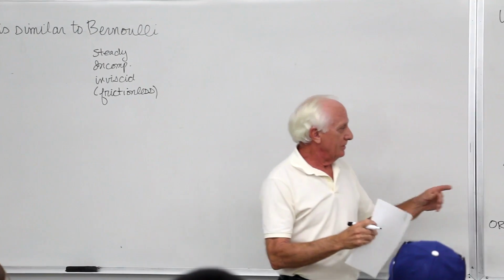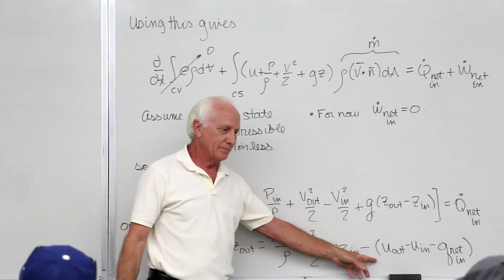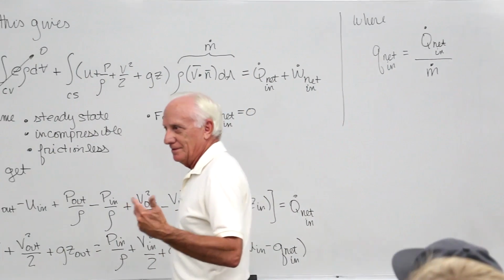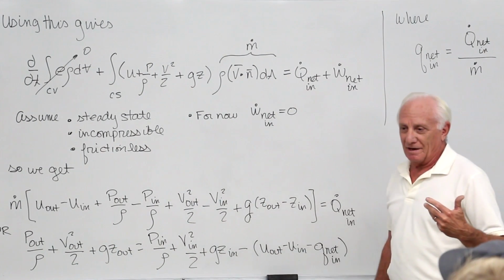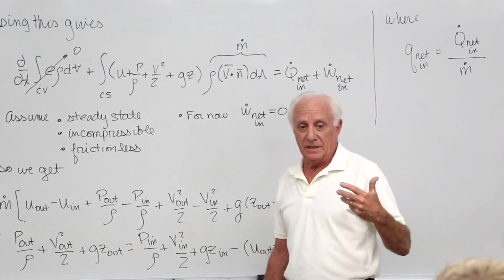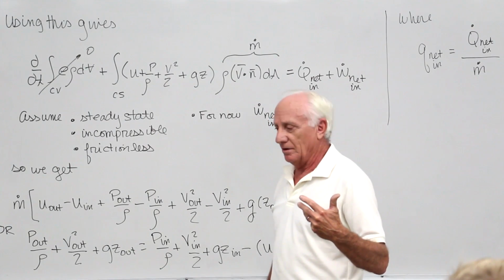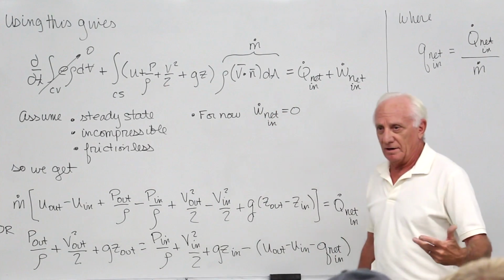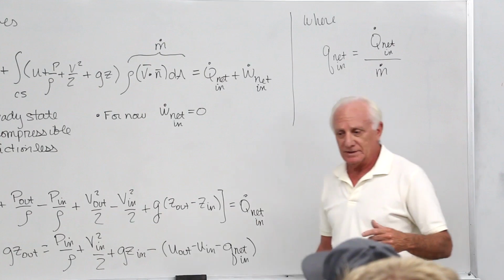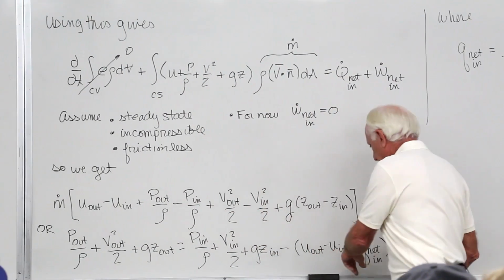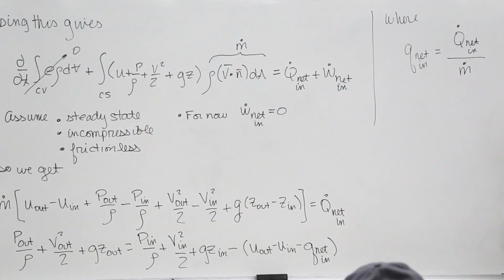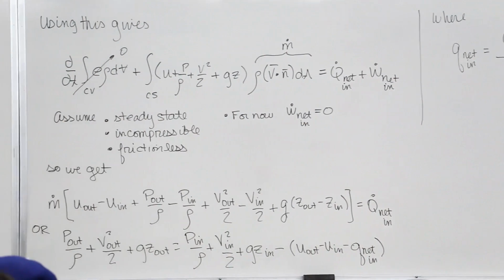That term there must be somehow tied into friction. And if we have friction in something like a turbine or a pump, what happens? Friction eats up the available energy. That's why a pump or a turbine is not 100% efficient. It heats the pump casing and the water inside the pump. Is that useful energy? No. The bearings on your car wheel and the drive shaft heat up due to friction, which takes power away from your engine to drive the car. So what do we call this term? We call that the loss of energy due to friction.